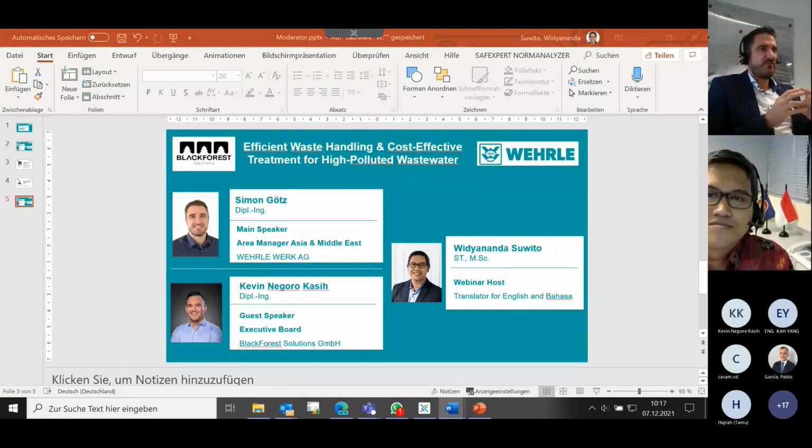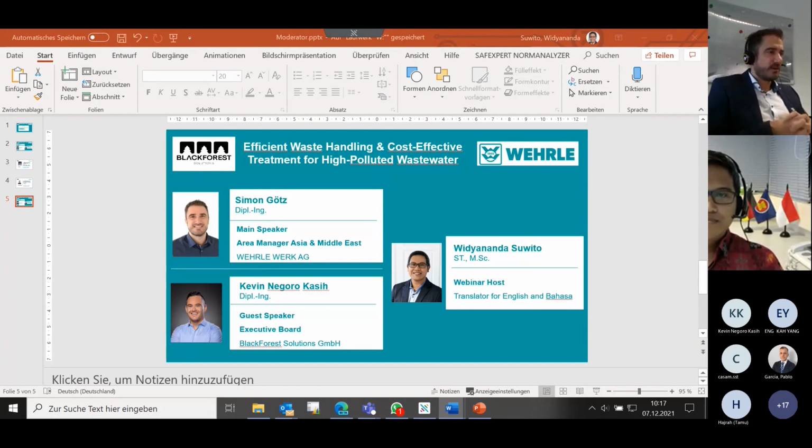and not with pure oxygen. If you have a really low alpha factor, out of the 20% oxygen in normal air, you do not get sufficient oxygen into the microorganisms. But if you have a really high alpha factor, the 20% in the air is enough, out of which a good share goes to the microorganisms. Therefore, we do not need pure oxygen. We are running the plant really successfully with normal air, which helps us have a much lower OPEX compared to pure oxygen.